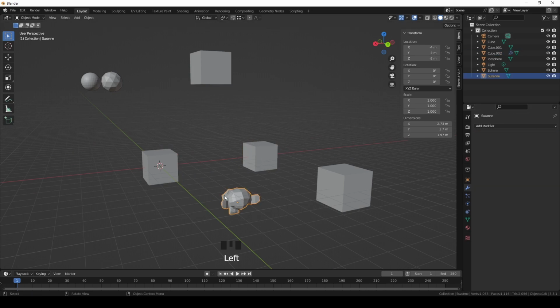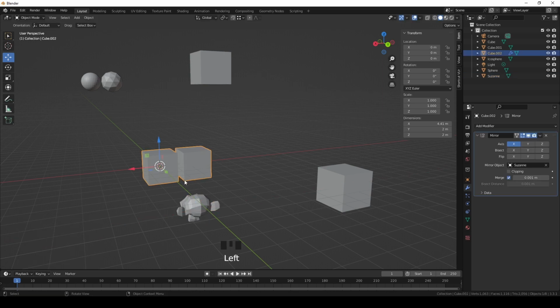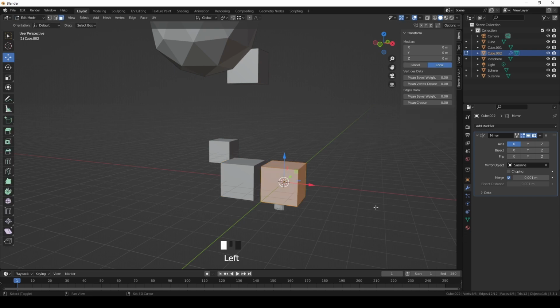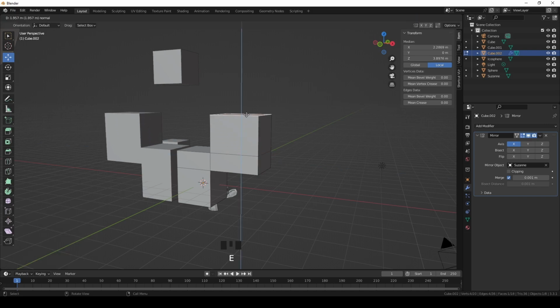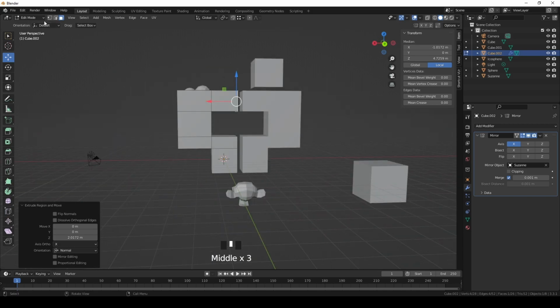For now, if I select my monkey object and change its origin to any location, as you can see, my mirror object follows my object origin point at the same time. So I can go into edit mode to make some kind of object and create things, and I cannot use my object origin, but I can use a mirror object like a monkey.